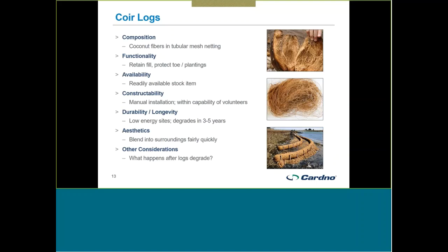It's also a planting medium, and it's biodegradable. That's, I think, one of the biggest reasons that it's used, because in those instances where folks are hesitant to use more durable material for aesthetic reasons or whatever, biologs are perceived as being a greener solution because they're biodegradable. They're made out of natural material. They're readily available. I think last time I looked for them, there's definitely specialty suppliers that provide them, but I think you can even get them from Lowe's now as a specialty order item. I don't think they're on the shelves, but there shouldn't be any trouble getting these if you want to use them as part of your design.